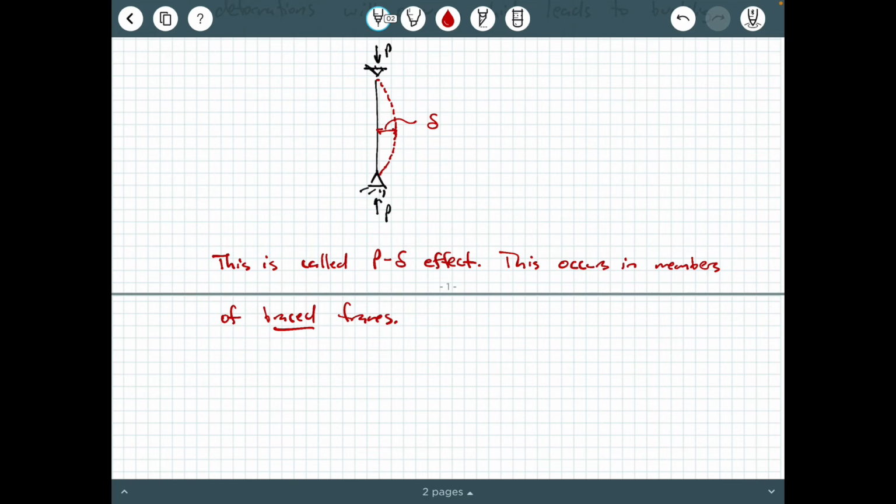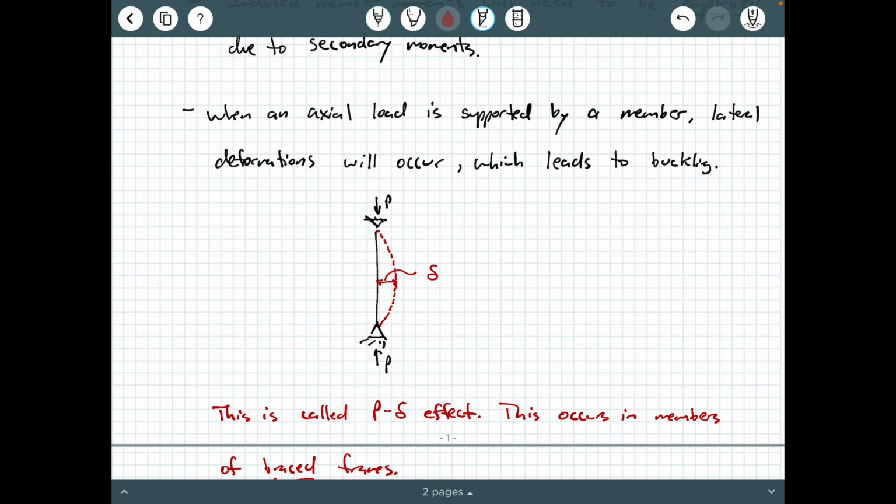And so again, what happens is you have this axial compressive load that causes this buckling mode to occur, and when this member bows out and creates this deformation little delta, you then generate a moment arm, right? You have this little moment here that's generated by P little delta, because now your line of action of P is at some distance away, little delta, from where the member is now, okay?